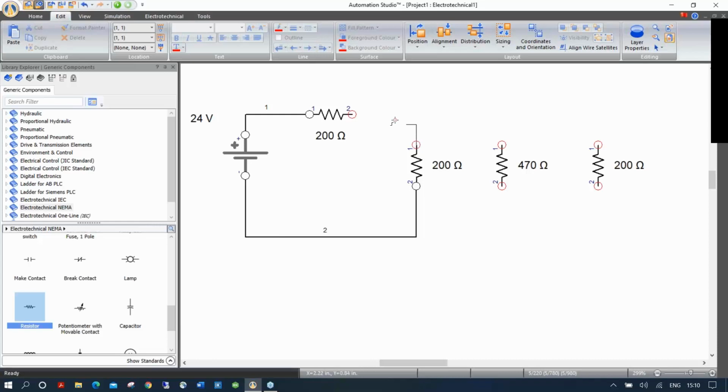Okay? I'm going to connect this here. Then look what's going to happen when I click this one. If I click here once, I want to connect it here. But you see, I don't have a connection point, so I can't connect it. But if I double click, the software is going to make a junction. But this is electrical. I cannot really put a T in a wire, you know. I would have to do a splice or something like that, okay? So the software is asking me where I want to connect this. So to this port or this port. And if I choose this port, you see, if I click on the wire, it shows me all the way where it goes. And this one also connects to this port, okay?